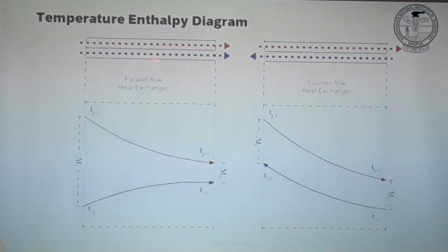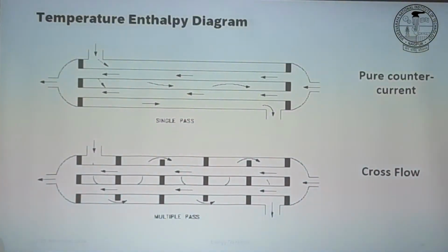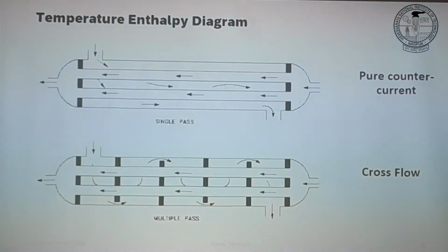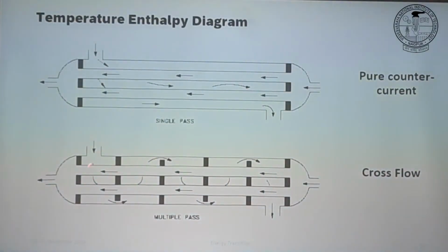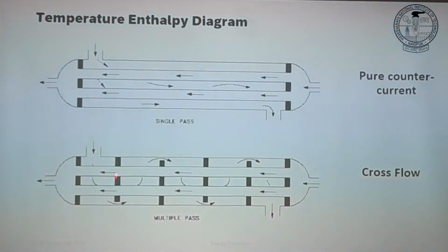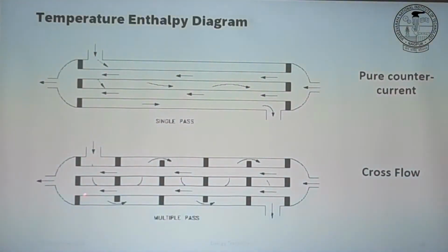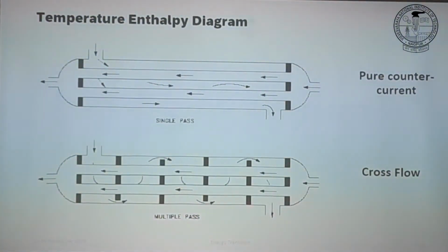So we saw here that's co-current, that's counter current. Right? And you see any heat transfer equipment in the world or in industry, it will never have a pure counter current fashion. Apart from double pipe exchangers, which are rarely used nowadays. So if you see here, in this region you have cross current, because this is cross. Cold fluid this way, hot fluid this way. In this way, it's also cross, but overall is cross counter. Right? So it's not pure counter current.